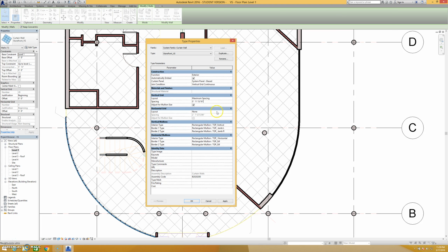So if you need to have horizontals, then you have the option for specifying what type of mullion you want. Now the Revit standard mullions that come in are just the first 4 or 5 you see here. So none, which will give you a line that divides those glass panels, but it won't give you any modeled component in between them. This is a good way to show silicone joints where the glass meets itself and there's nothing holding it up,